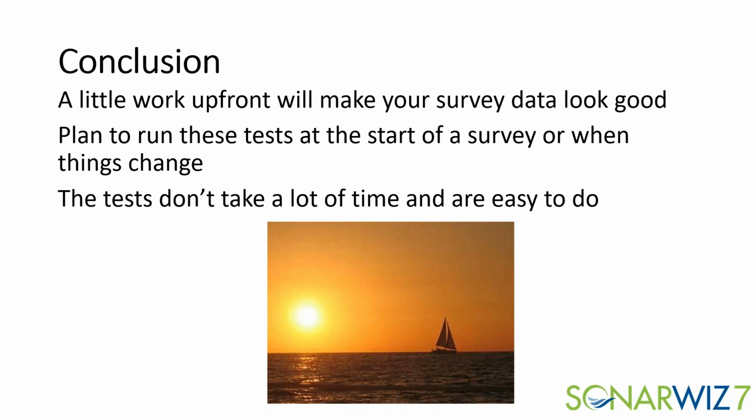Sometimes you get frustrated because you can't find the feature on the bottom for the patch test, or sometimes the reference area is on a slope and we have to go a little bit further downriver to find a performance area, reference area. So they don't really take a lot of time once you have the right area, and they're generally easy to do. Once you run through the bathymetry processing, things are just straightforward from there.